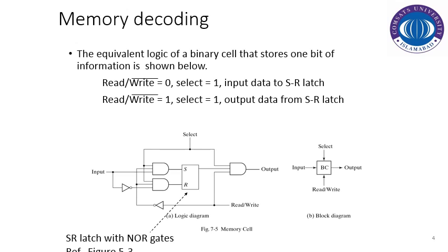Where density and cost are important, that the memory element should be cheaper with higher density, and we can compromise on speed and performance, then we'll prefer the dynamic RAM. And where we can compromise on density, chip area and cost, and we want the implementation to be high performance, efficient, with more speed as compared to the dynamic RAM, we'll prefer the static RAM here.